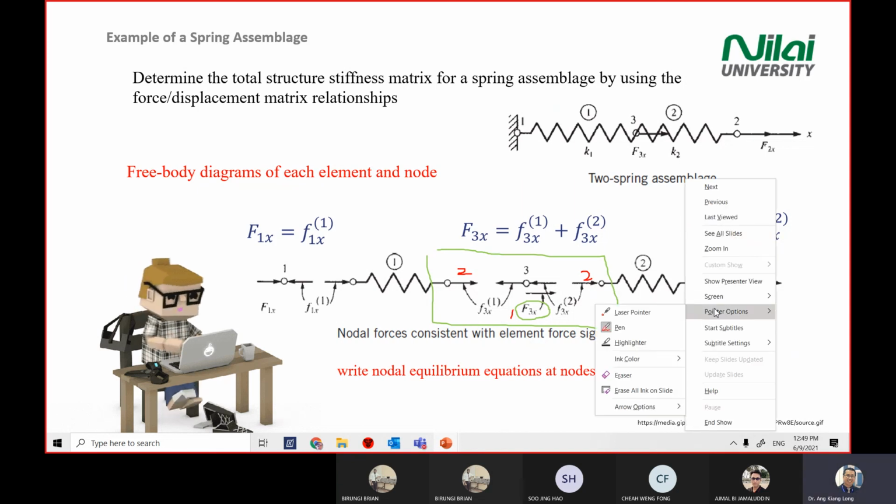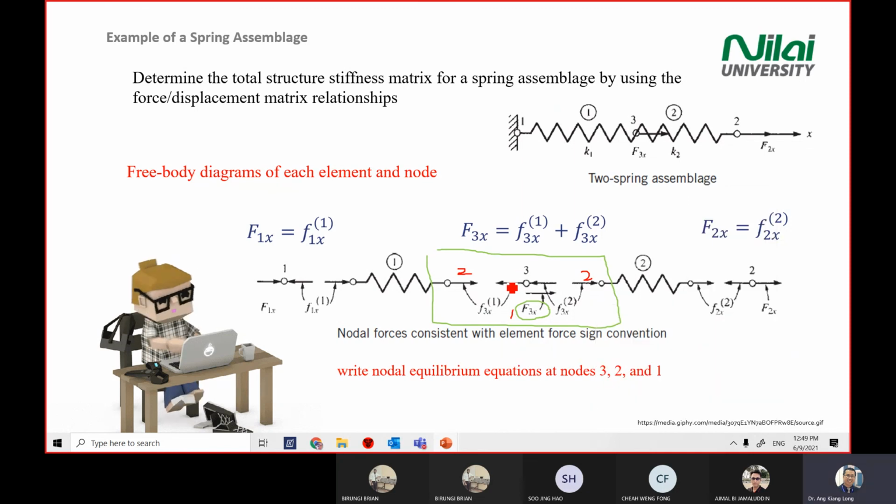Then after that, when you have solved the connecting point for the elements, you go back to the point itself. Then you counter the forces of the connecting point. So I will write number 3 here to counter this one. Then this one will counter this one. So I'll label it number 4.